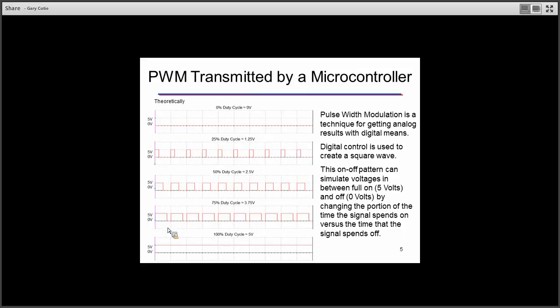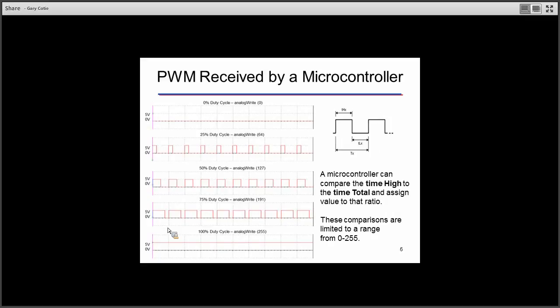In our case, that translates into a controller that controls a motor, and the motor will do different things based on the pulse width. Actually, what's happening is you're trying to use an analog signal, even though it's digital, just a 0 and a 1. You're using the pulse width to act like an analog signal to change speed on a motor or change direction on a motor.